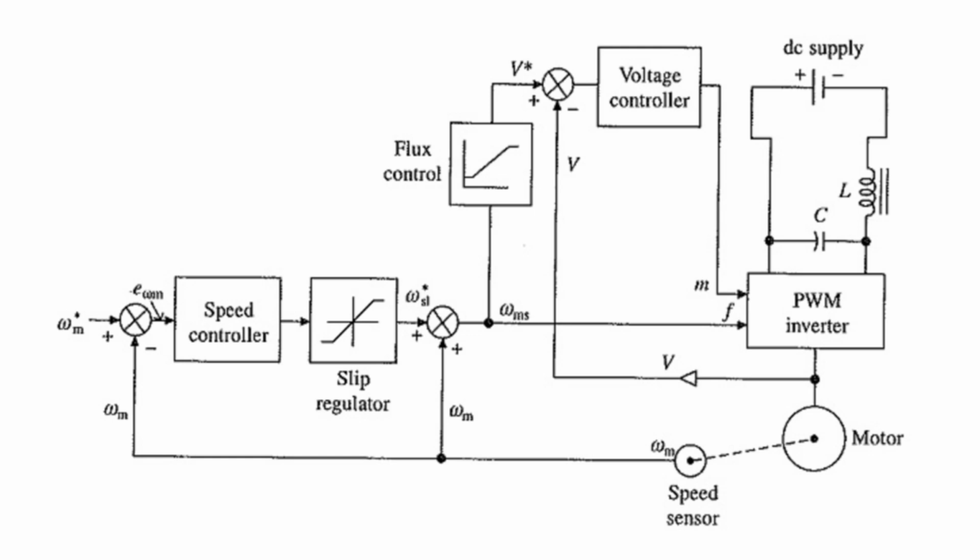This is the block diagram of the closed loop circuit. Generally, I have mentioned the inner current control loop and the outer speed control loop. Here, for the induction motor, the current is controlled by controlling the slip. That's why you are saying slip control. For the induction motor, current is controlled by controlling the slip.